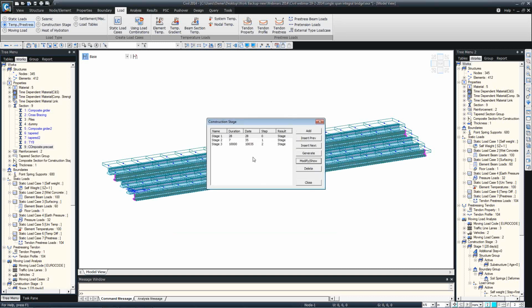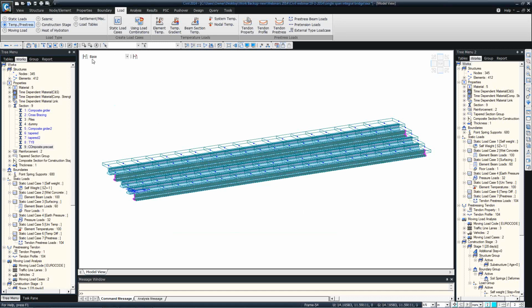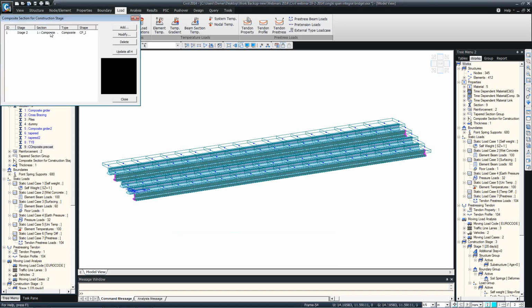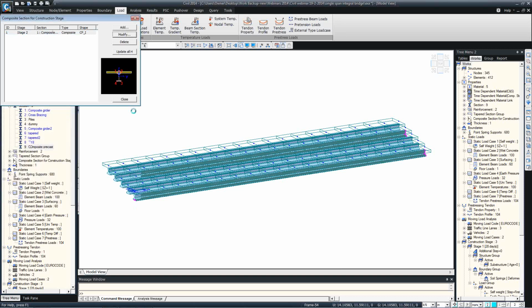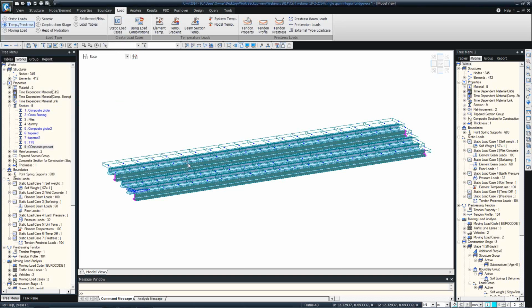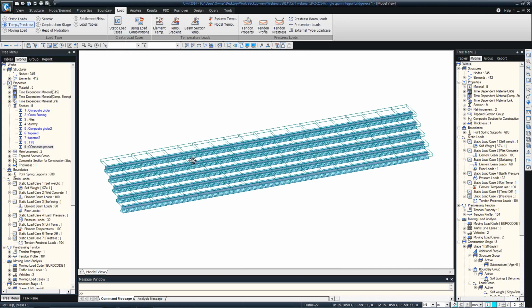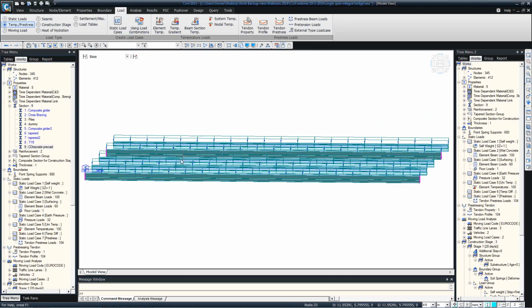So then the parts are considered separately from this option, where you specify the materials for girders and materials for your slab, and the age for both of them, and creep and shrinkage will be considered for both the materials. So that's how we do the precast concrete bridges.